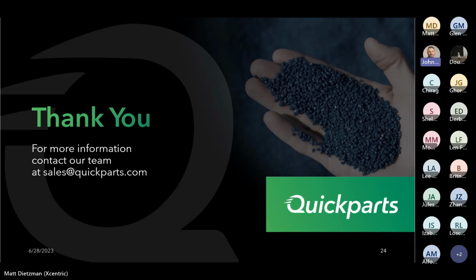Another one, any thoughts on replacing PPO glass filled with polycarbonate glass filled? Again, don't know the stats offhand. We'd have to look at and compare data sheets, but that's something we can definitely look at. Yeah, you have to look at your shrink rates. You have to look at various issues, which again we can definitely guide you through for sure.